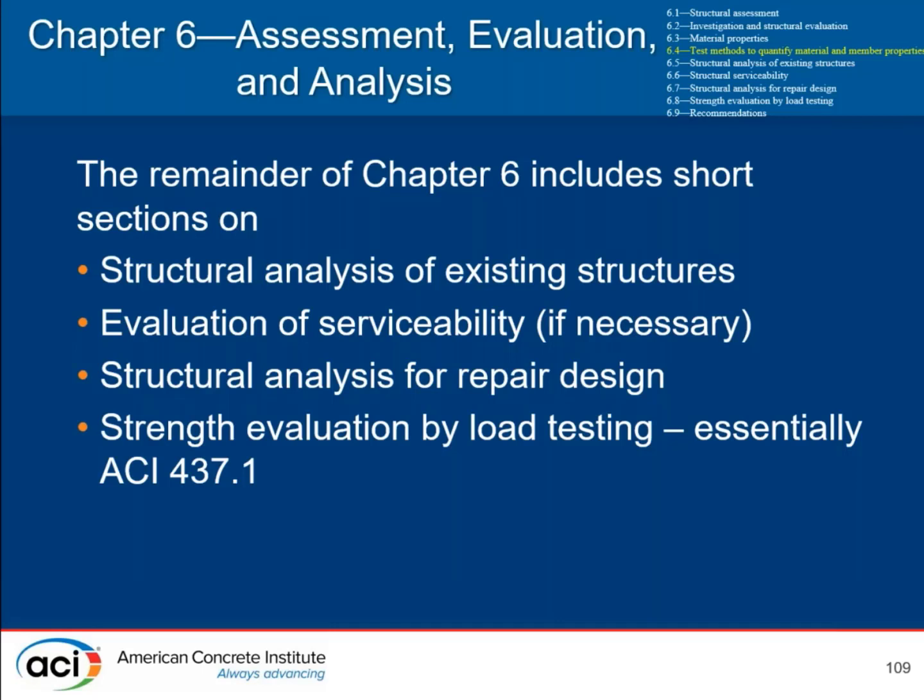Carrying out structural analysis for repair design, that really focuses on how, when you're designing a repair, you're probably partially disassembling the structure and reassembling the structure. And so at each step of the repair, the safety of the structure has got to be assured. And there's a section on structural evaluation by load testing, which is essentially the provisions given in ACI 437.1.